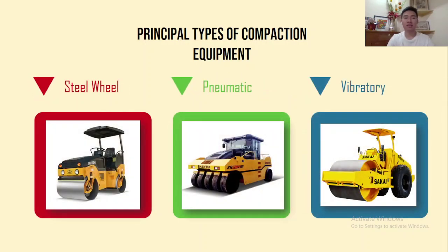First, let's discuss what is a steel wheel. It is the tandem or double drum roller, which has one steel drum in the front and one in the back. The efficiency of the tandem roller comes from the two drums, so an entire section of a highway can be flattened and paved quickly and efficiently. These rollers are great for flat or gradual surfaces like asphalt, but because they have very little traction, they're not recommended for anything specialized.